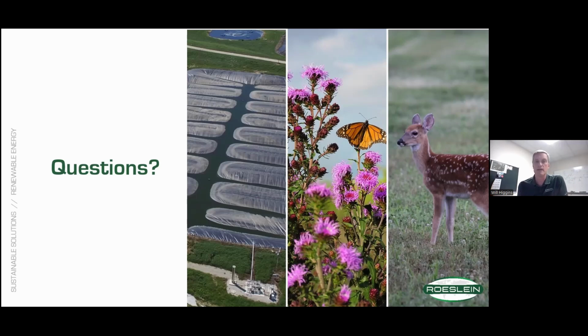We've gone in and used a high flow rate pump to blow that pile up and push it away from the end of the pipe to get us more time. We've been able to do that pretty routinely without having to peel back the cover and actually get in there with equipment to remove the solids or sludge.